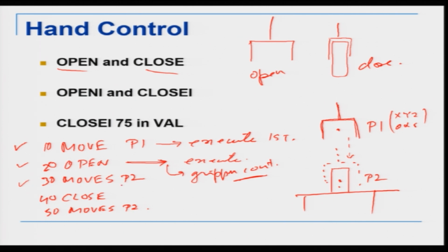Now, what can happen here is the gripper controller, the gripper here will take some time to open, right. So, this is a physical system, the gripper is a physical system. So, basically when the gripper is here, what it basically means is that in this line the gripper comes and positions here. Second line is open command, and on the open command the compiler tells the gripper controller to open, the gripper controller opens, and then immediately it moves to the third line.